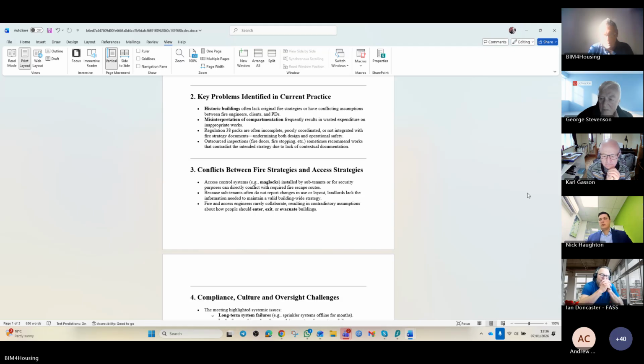Absolutely. I mean, if I put a smoke control system hat on, if we were working on a system or testing a system or commissioning a system, or servicing a system, whatever, we would always try and do an end-to-end test. So even things that weren't part of our supply, but which interacted with us, we would always expect it to be demonstrated to us, so that when we sign something off, we can tick the boxes and verify that the system does actually work.